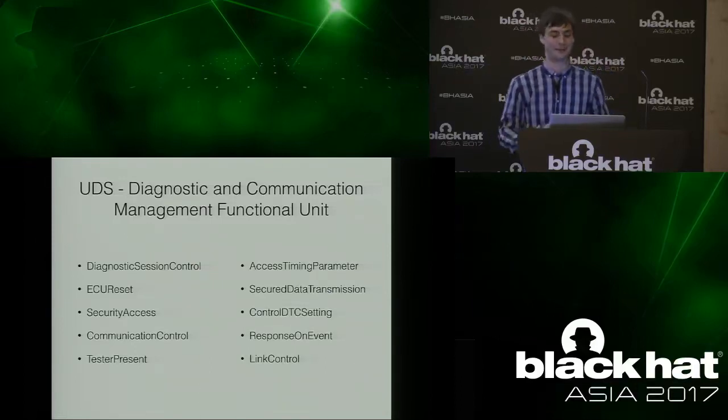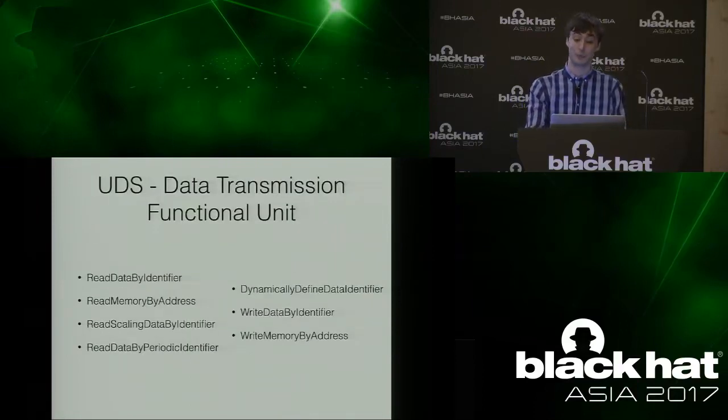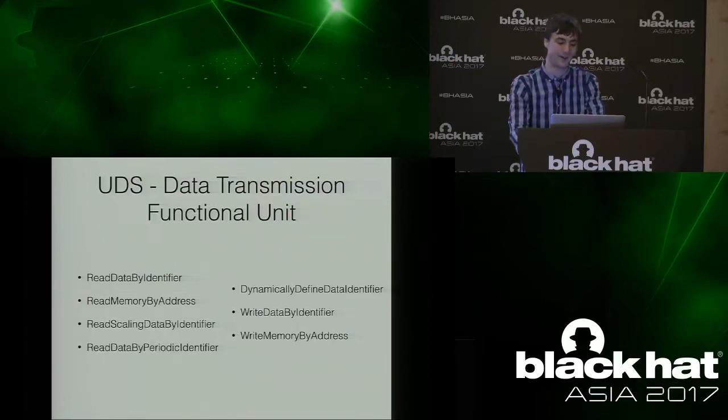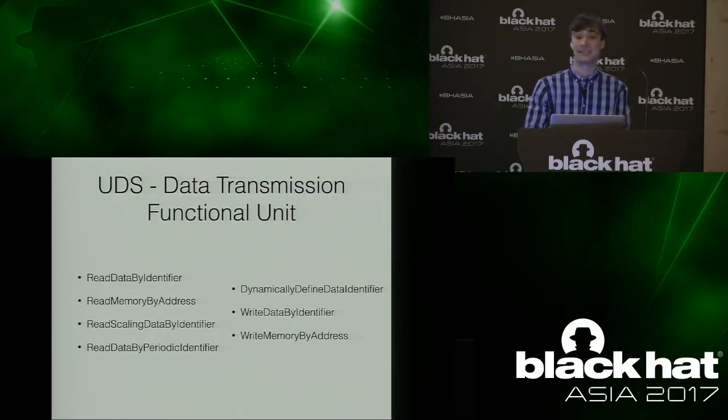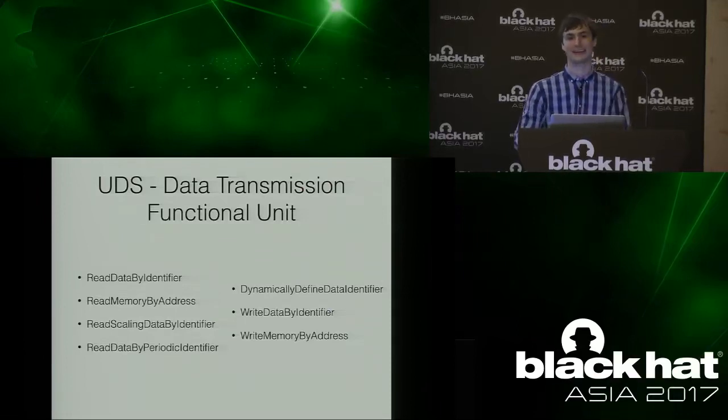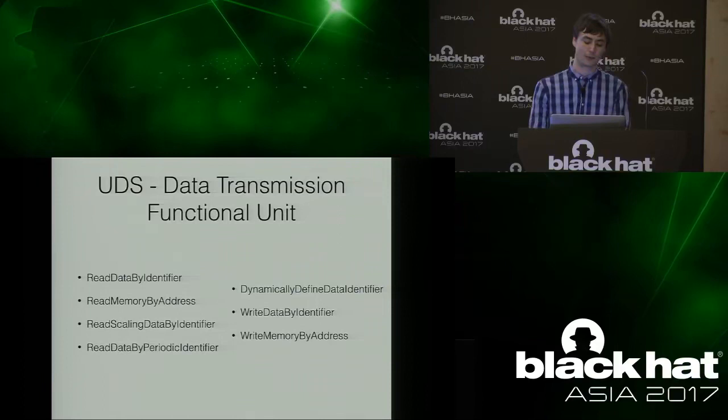This is all just the stuff that makes diagnostic work. This is like the foundation of being able to set up your sessions and do that sort of thing. The next parts are actually the more useful bits: read data by identifier and write data by identifier. If there are two services you should be interested in, those are probably them. There's a database of these data identifiers in the vehicle or in the ECU, and they all just have a number that's assigned to them. That usually has a specific representation based on either the OEM that made the car or, in some cases, whoever made that actual controller can define them. And what those contain is just some arbitrary data. You don't really know what's in them, but you can read and write them.